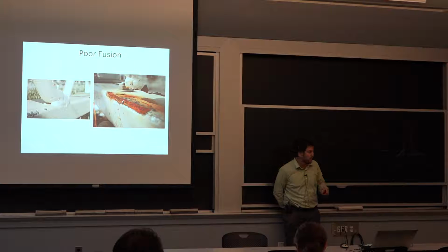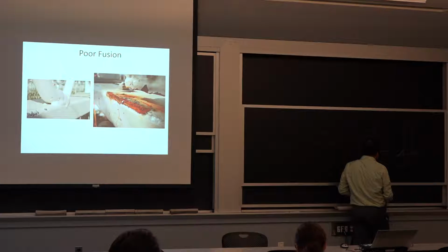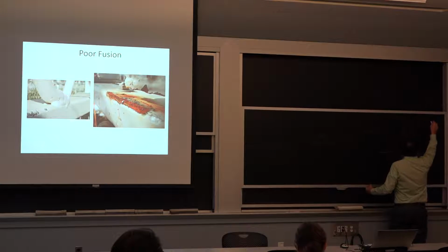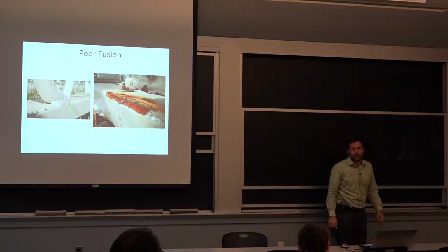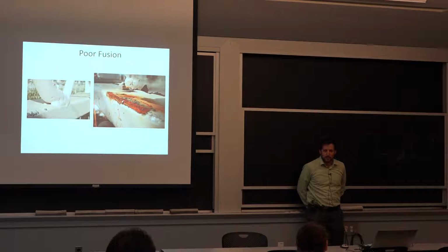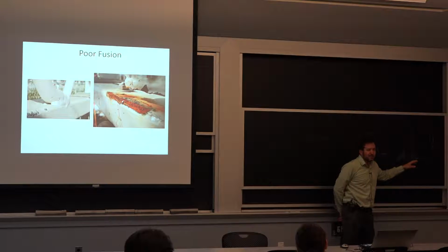But the process needs to be very optimized, because if you go from almost vertical to what we call an overlap, the overlap defect is essentially the bead that's going to extend and have a slope going the other way. That is a big no-go, I would say, even for the fitness equipment. So I think hopefully it gives you a little bit more of a perspective of why we are able to